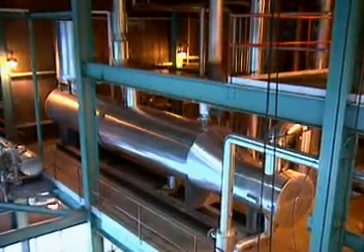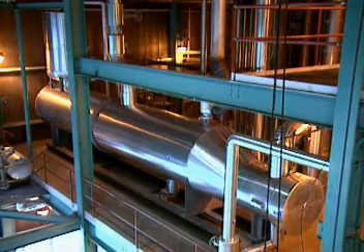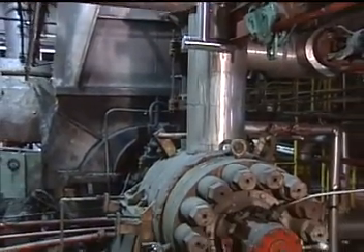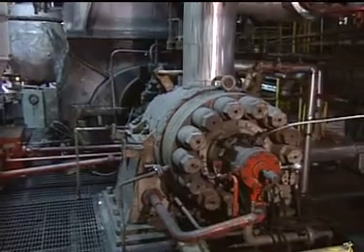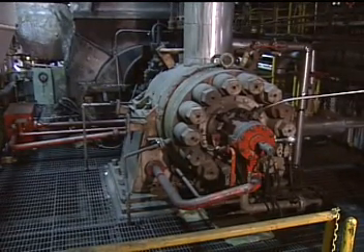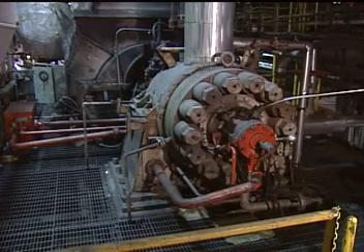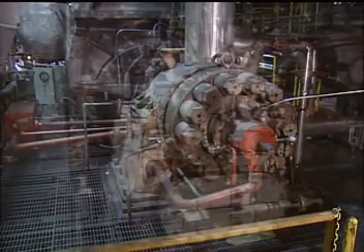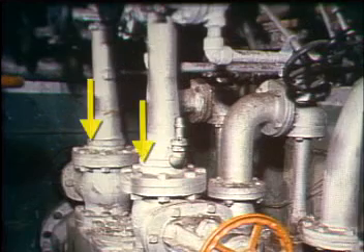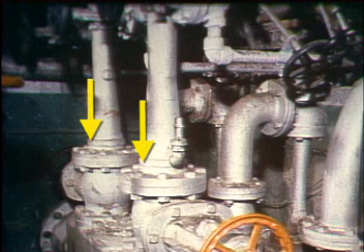In some plants, the makeup water purification systems include evaporators that use auxiliary steam to heat the water. Also, auxiliary steam is often used to power equipment such as turbine-driven boiler feed pumps. The auxiliary steam is supplied to the turbine, which operates like a main steam turbine, except that it drives a pump instead of a generator. In many plants, air ejectors use auxiliary steam to help maintain condenser vacuum. The jets of steam from the ejectors create a low pressure that is used to remove air from the condenser.